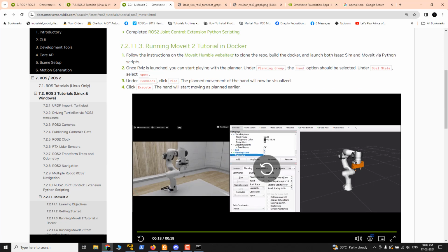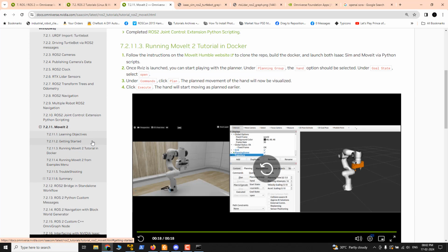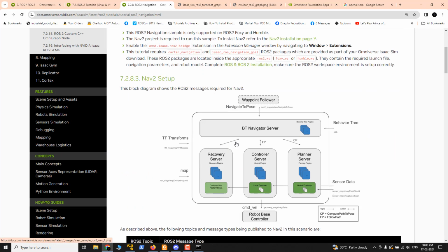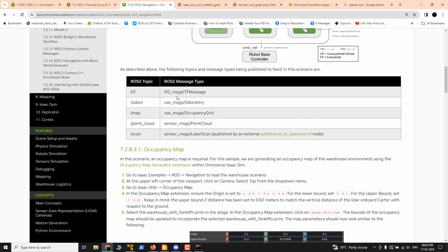You don't need to create something; everything can be done inside Isaac Sim, and you can run the ROS2 navigation stack from that, because you are getting all these topics. The ROS2 navigation stack only cares about the topics, right? If Isaac Sim is giving all these topics, then it's ready to go.